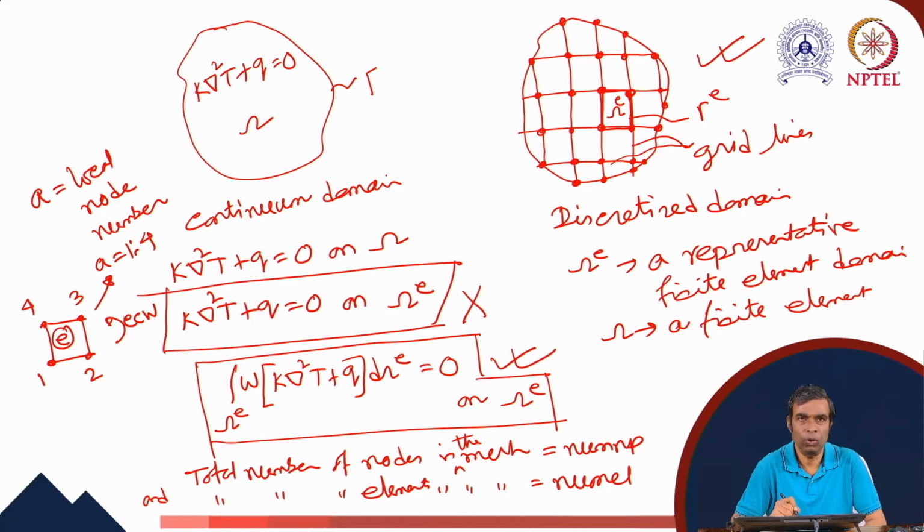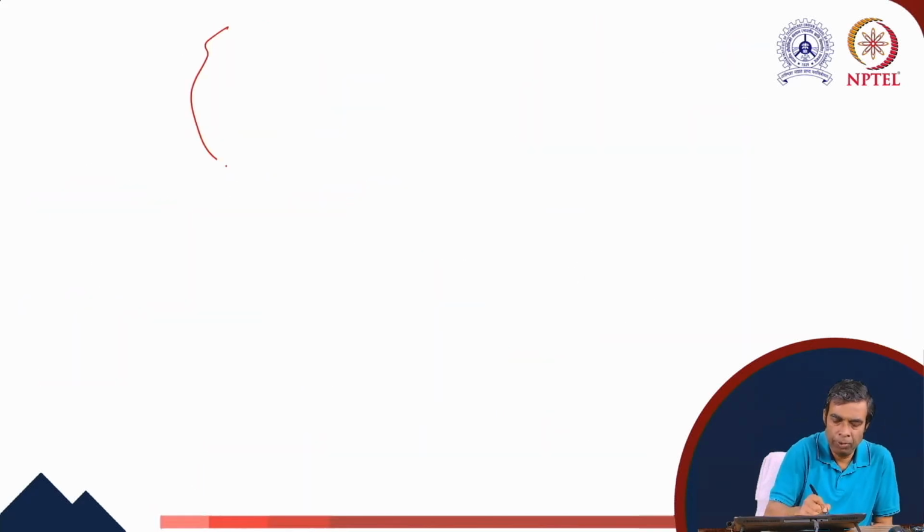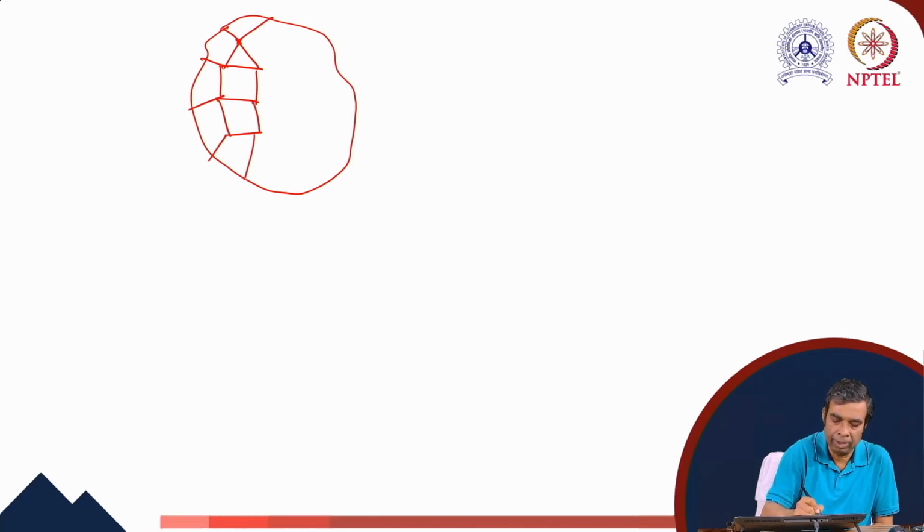Now let us show the case of an unstructured mesh working on the same domain. The domain which we have shown here, we can now split into quadrilateral and triangular elements where there is no specific structure present. So let us first arbitrarily generate the mesh. We decompose the domain into a finite number of non-overlapping subdomains or finite elements.